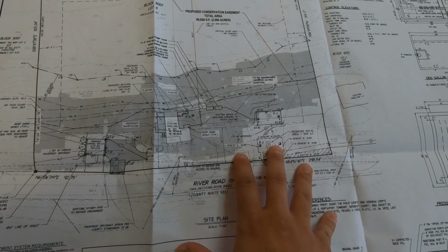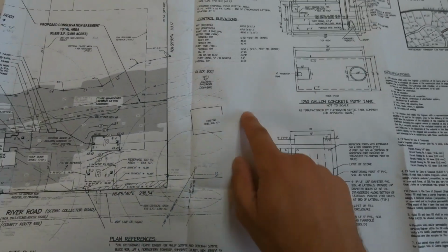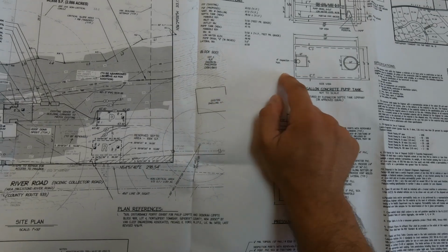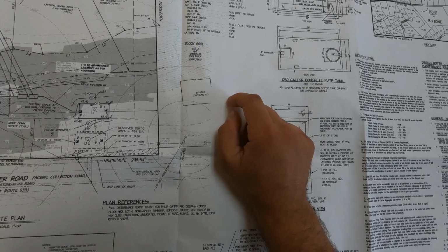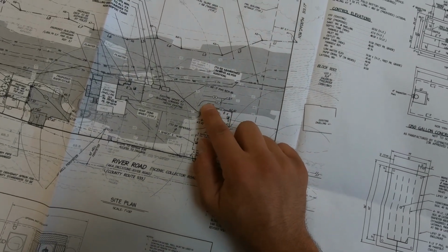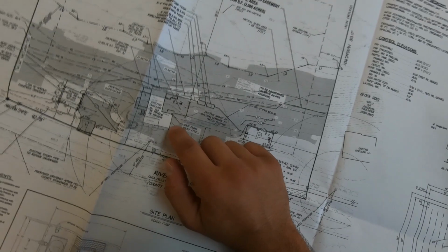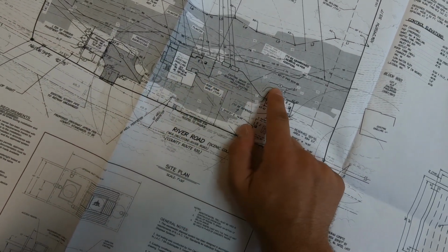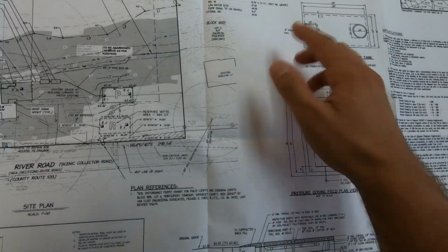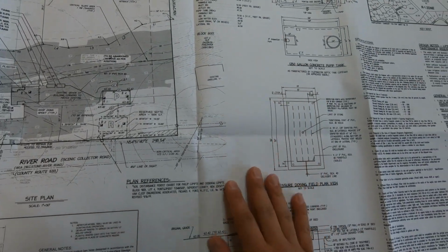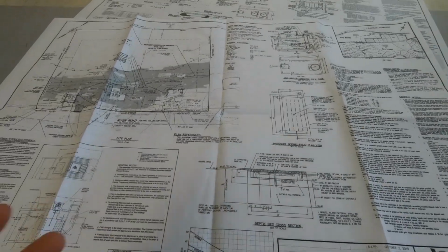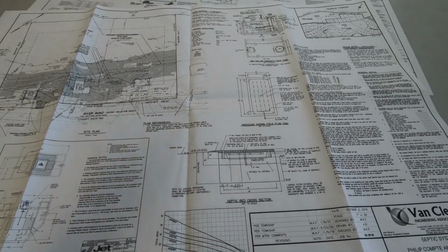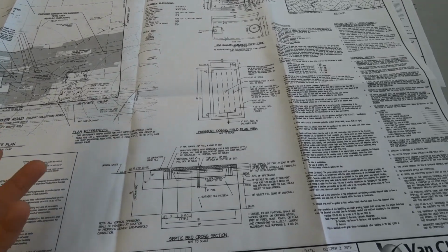Once you take all of those measurements, a lot of the time I'll find some empty area on the plan and I'll write down the as-built measurements to each of the features. I'll label each of these features. So this corner would be A, B, C, D, and then building corner would be 1 and 2. And so 1 to A would be this, 1 to B would be this. And I would write all of that down here just so that somebody who's looking at the plans can take a look at it. You'll see that as part of the inspection that I'm going to be doing for this project, but I'm just explaining it to you ahead of time.